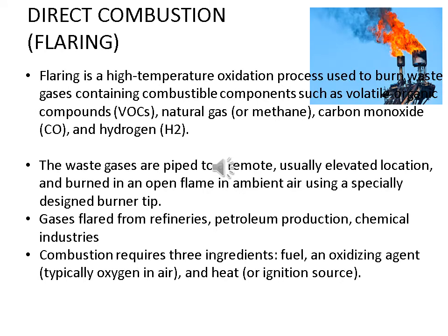Direct combustion or flaring is a very high temperature oxidation process, mainly used to burn waste gases. That gas contains different combustible components like volatile organic compounds, natural gas or methane, carbon monoxide or hydrogen. With the help of these combustible components, we burn the waste gas.